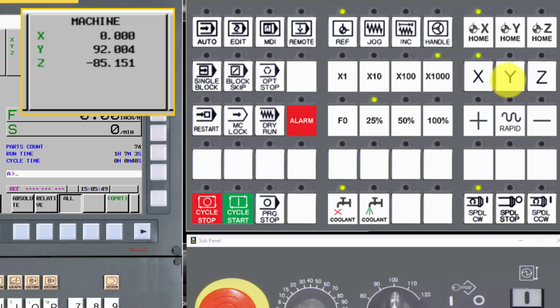Check the Machine Tool Builder's operator manual for specifics on the reference or home feature on a particular machine tool. With this particular machine operator panel, you can return an axis to its home in Ref mode by selecting an axis and holding down the -jog key until the machine position is 0. Note that the axes move at the rapid rate.